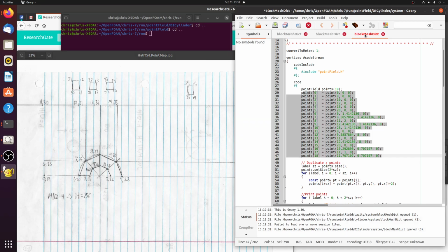One thing I've done is, instead of foamCloneCase and cloning a new case from a past tutorial, like the small rectangle that we did last time, I actually copied the tutorial from the built-in tutorials, and then I changed the points according to what I told you over here, which from this point to this point, point 2, is 10R, and R is 1 centimeter.